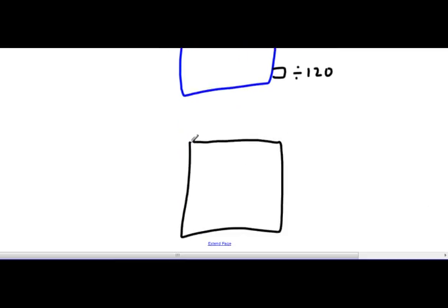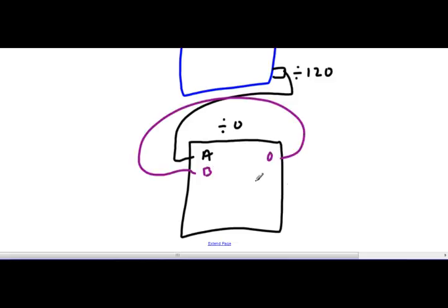Well, I can go back to another divide by 10, bring that into the A input, bring the 0 output over into the B input, and then that's Q0, Q1. And now coming out of Q1 would be divide by 480.